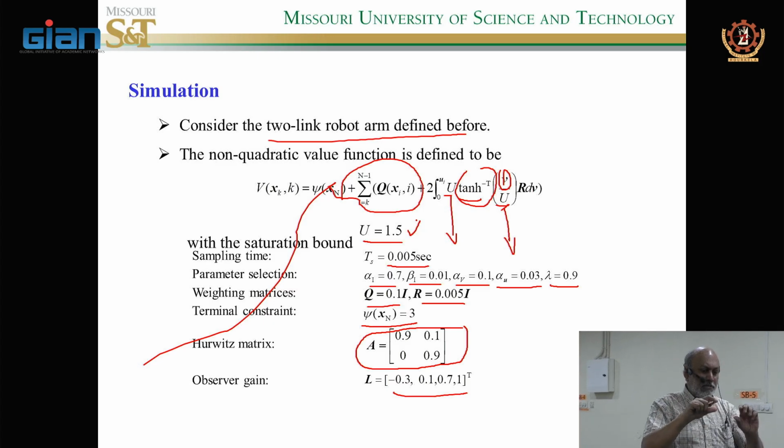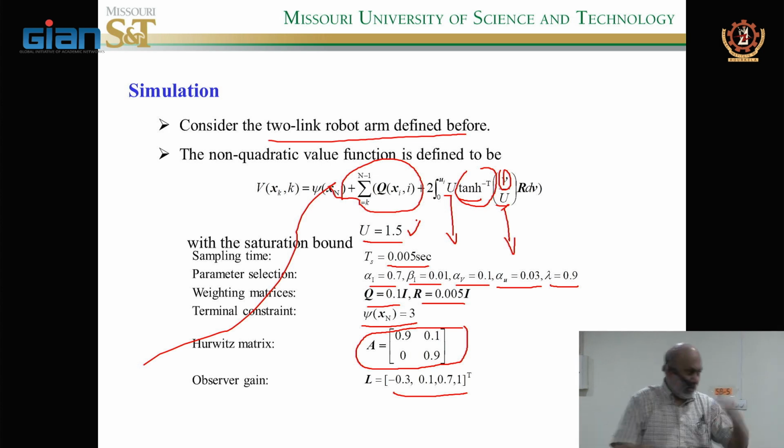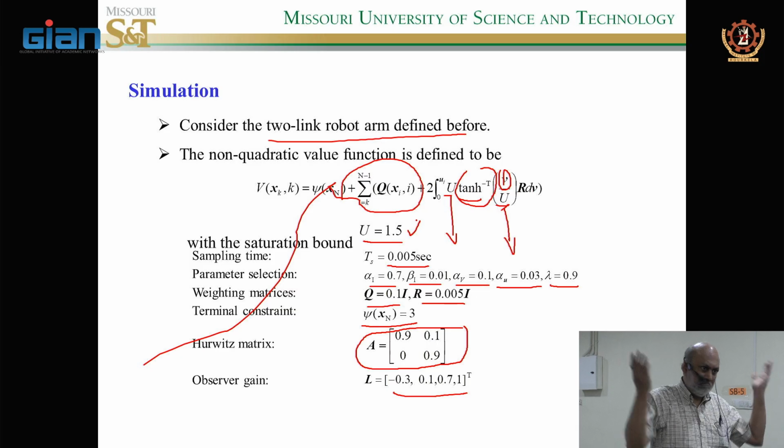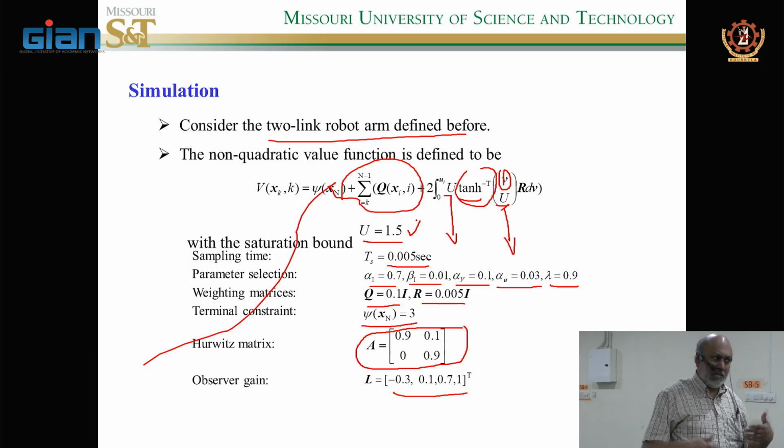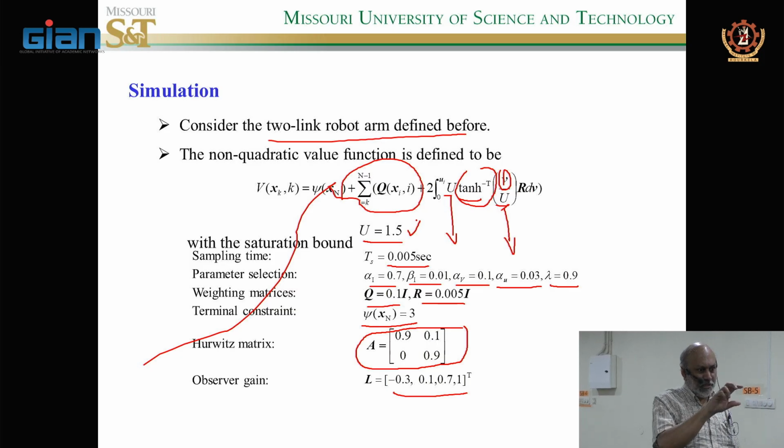Basically you construct the trajectory by another state equation. Then you construct the augmented system with the trajectory generator state and the system state. As long as it's controllable, you can do the same design. So you use the error, which is the desired state minus the trajectory.